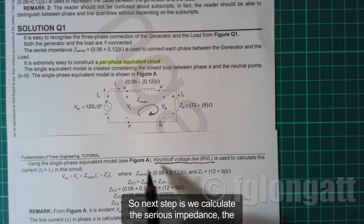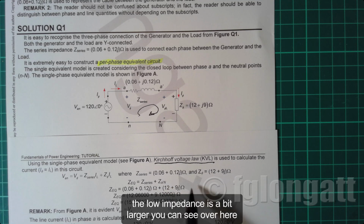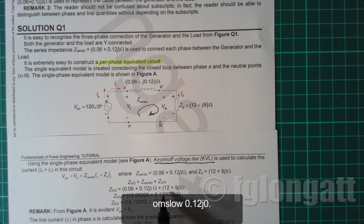So next step is we calculate the equivalent impedance, that is basically the series impedance plus the load. The series impedance is very low, 0.6 plus j0.12. And the load impedance is a bit larger. You can see over here, 12 ohms plus j9 ohms. So for you, it's very simple. Here, this is the rectangular form. You can see that the rectangular form is 12.6 ohms plus j9.12 ohms.